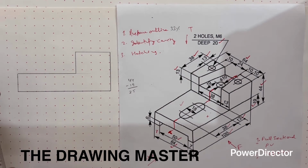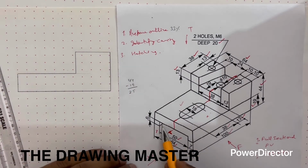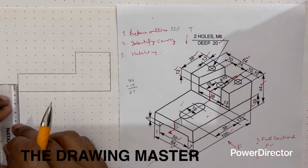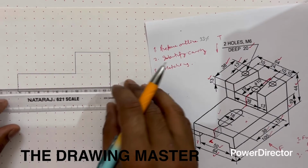So now let's identify the cavities here. In this whole object, this is the first cavity. This is the hollow part. Here in the base, only this part is solid. Only this is the solid part. So 6 mm height is there. So at the height of 6 mm, draw a line.